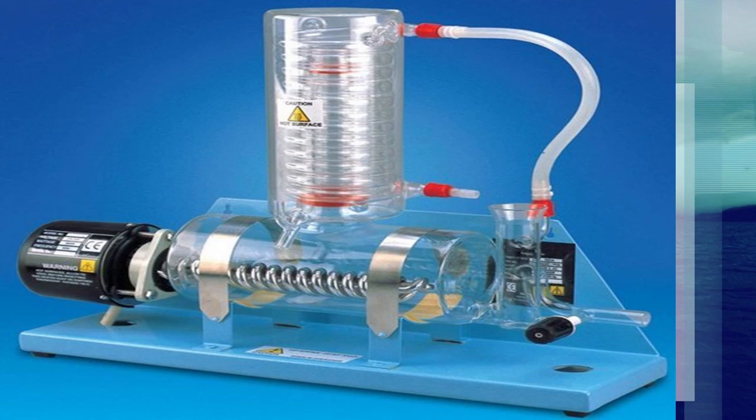In industrial chemistry, distillation is a unit operation of practically universal importance, but it is a physical separation process, not a chemical reaction. Distillation is a method used to separate the components of a liquid mixture that depends on the distribution of these various components between a vapor phase and a liquid phase. This requires that the components in the liquid mixture have different boiling points. Another way of putting it is that the components in the mixture must have different volatilities.